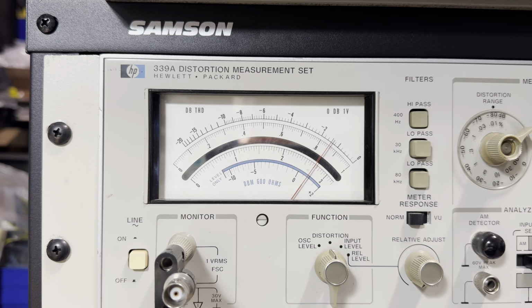The more an analyzer can reject the fundamental source, and the less it contributes to overall system noise and overall harmonic distortion, nonlinearities, the lower our measurement floor is, and the lower a measurement we can make. Of course, we're going to be limited to whatever the performance of our device under test is. So all of these things are going to play into our distortion measurement, and how low a measurement we can make and how accurate a measurement we can make based on the type of metering we use.